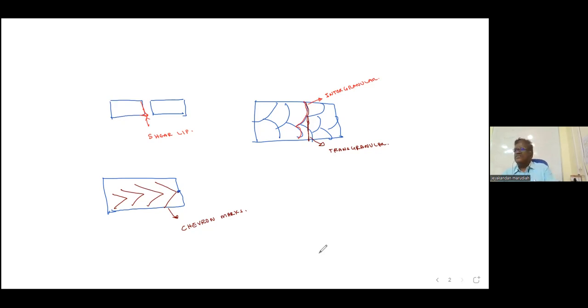Second one is the hydro test. Generally, brittle fracture will happen during hydro test only. You remember, once a tank withstands the hydro test, it will not fail during the service. So particularly for pressure vessels, I think 653 has no rules, but 510 and 570 have a rule. When you are doing hydro test in winter, you have to use warm water. The water temperature should be minimum design metal temperature plus 30 degrees Fahrenheit. The purpose of using warm water is that if you use cold water, it may promote a brittle fracture.